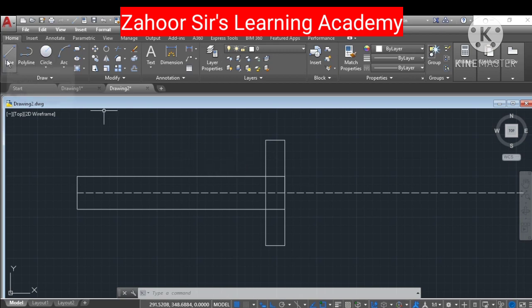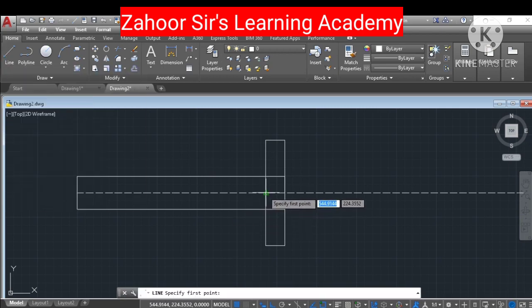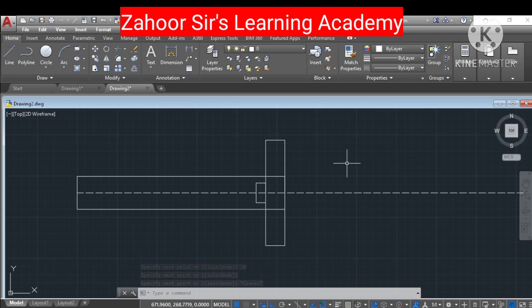So what I have to do for that, I'll take the align command again, and I pick from here. I'll go up 15 mm because the die is 30 mm, and half of that is 15 mm. Then I'll come out 15 mm, so I'll write 15, then press enter. Then again I'll go down 30 mm, enter, then I'll drop it here, then escape. So this is the horizontal tongue of the disc. So the middle disc has been taken care of.